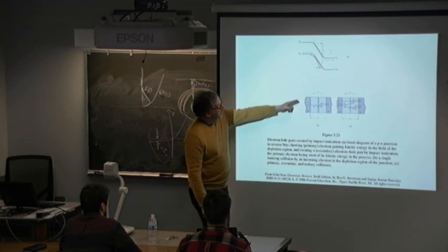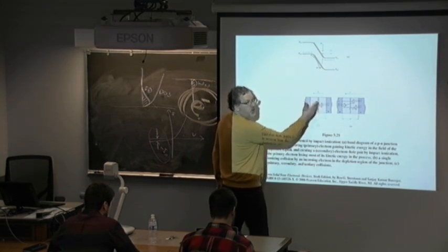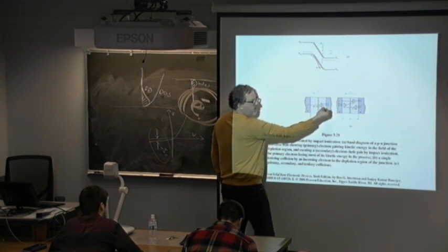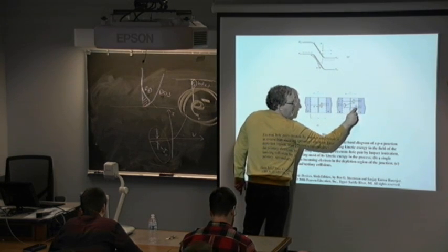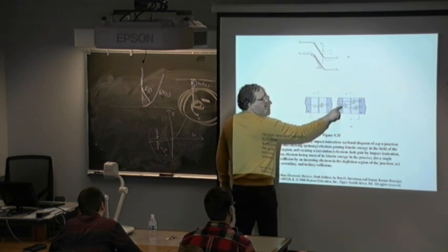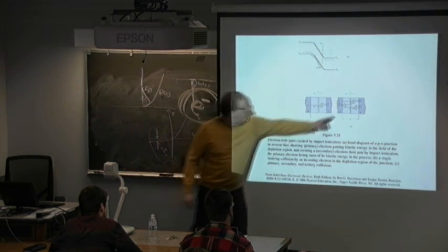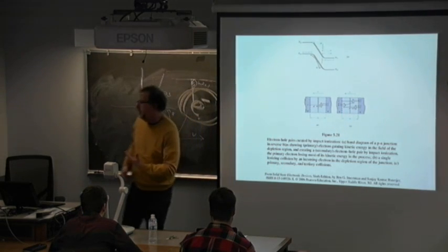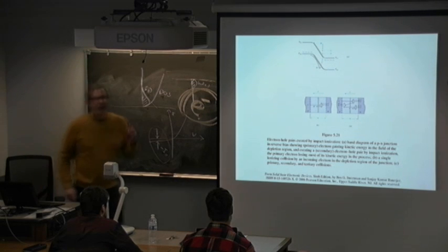Okay, so here's kind of showing that the carrier comes in, you get an ionization, and then it creates two more particles. And here you ratchet up the voltage, even higher electric field, and now the secondary electrons can create third electrons and so forth. And you get this avalanche runaway. It's kind of like a nuclear reaction runaway. Questions on that?